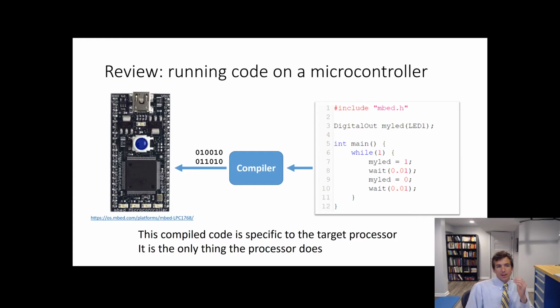So think back then to 200, which is the last time I know you worked on these things. I'm sure you've done them in the past. But this is the standard model of how you write code, right? So we're going to write some C code on the right-hand side of the screen here, just to blink a light, right? So we're going to include a library, embed.h, declare our resource, LED1, and then just go in a loop, right? And it's really important here to understand, what does this while one mean? Forever, right? While true and one is true, do this.